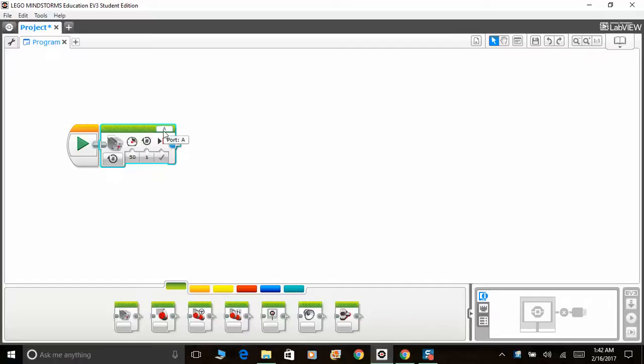So all the parameters can be set accordingly. Right here, this is the port where the specific wiring is connected to the EV3. So if you're set to port C, make sure that the wire that goes in the back of the medium motor is connected to port C on the EV3. You're allowed to choose out of the 4 ports A, B, C, D, and there's a wired function here, which will take a separate port. But I'll go through that in the next video.